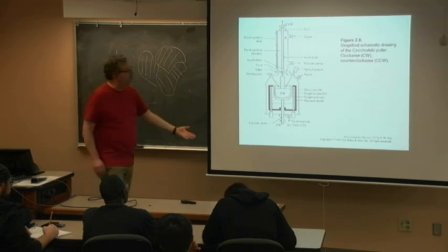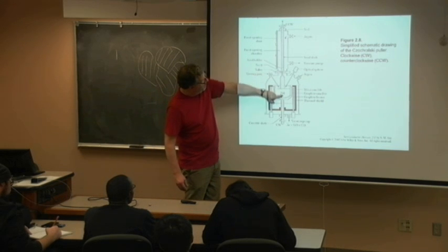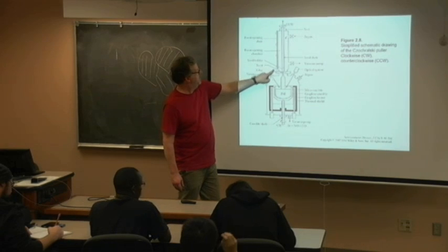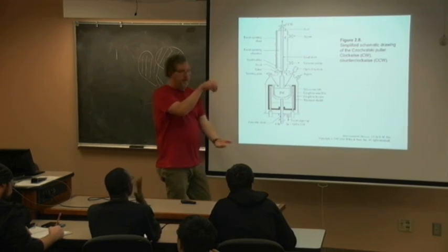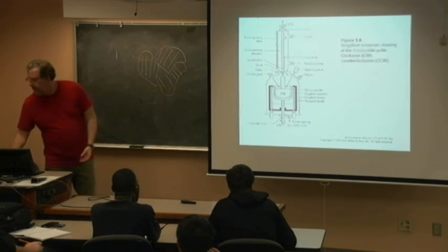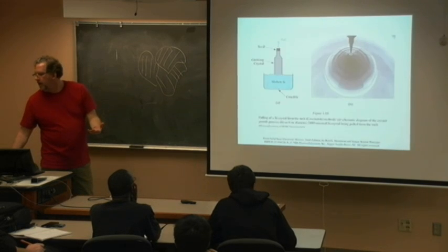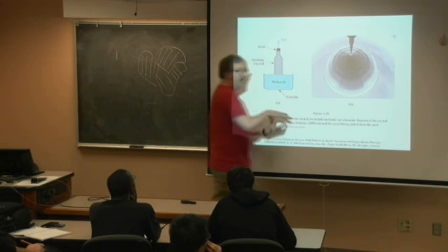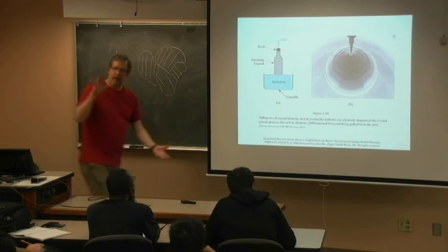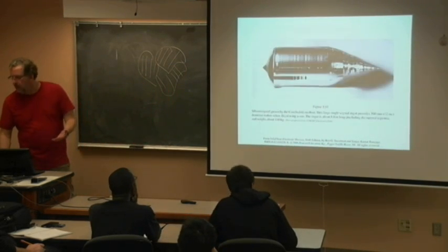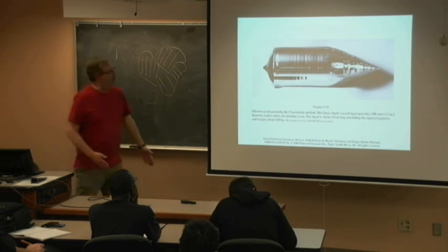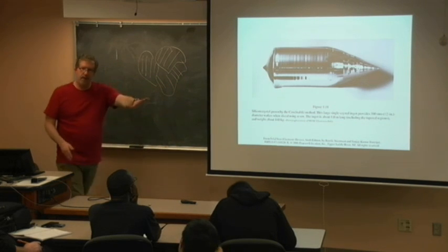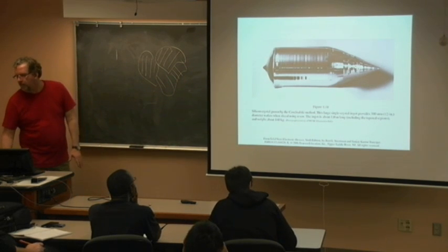Czochralski is a classic one. You're pulling those boules out of this molten silicon. You start off with the little seed crystal, and you pull that out. Pull it out like that, and there it is. So Czochralski's one way to make my ingot. And then what do I do next? I'm going to slice it, take that ingot, and slice it into wafers, polish them, and send them into my factory, my clean room.